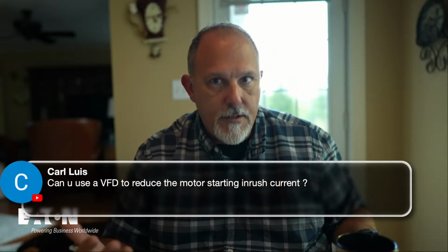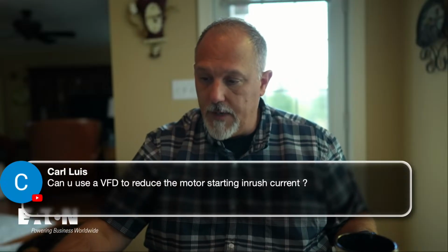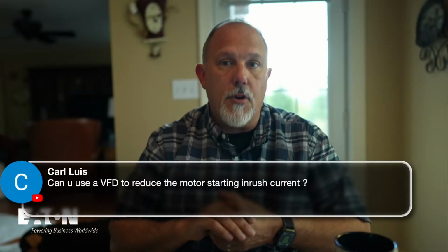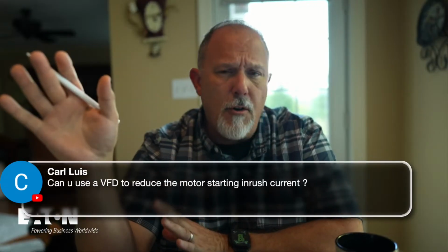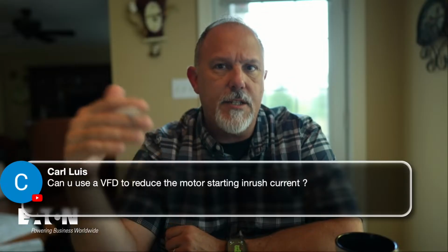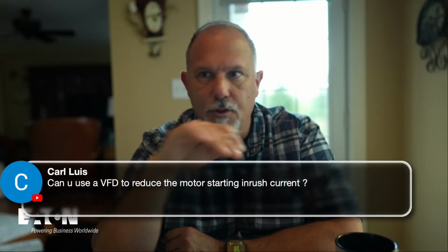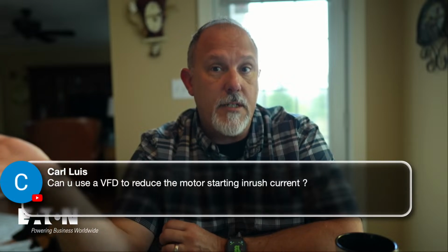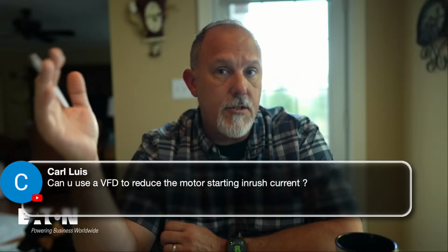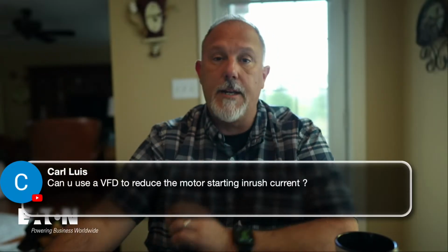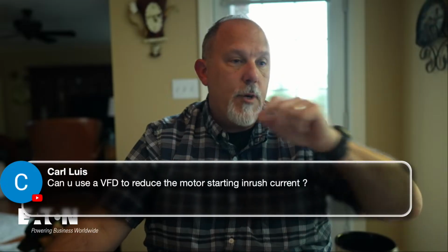Now, they come with a cost, price-wise. And they'll give you some third harmonics in some cases, depending upon the pulse of the drives. You may have to upsize the neutrals or whatnot. We'll probably get into that because this is an ampacity discussion, whether it's the phase conductors or the neutral conductors. Very good question, Carl. And hopefully this session gave you the bug to want to sit through more.